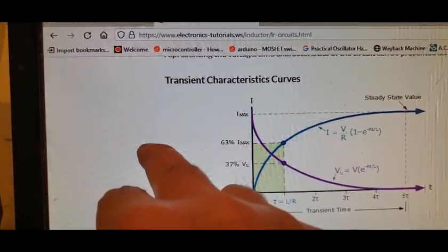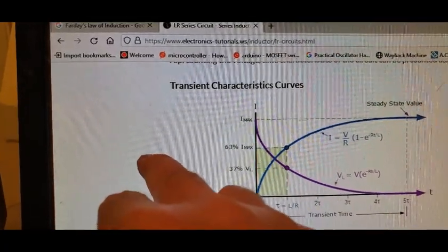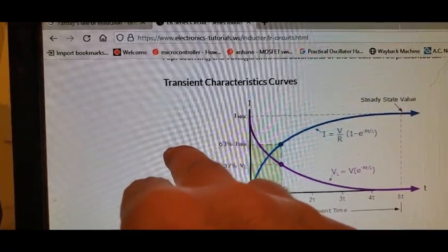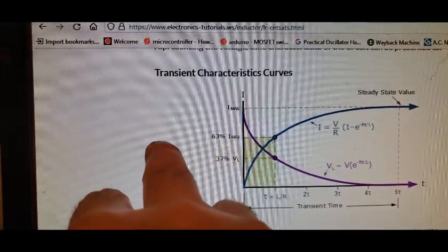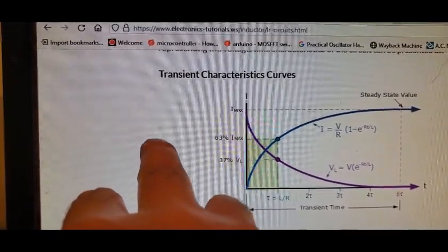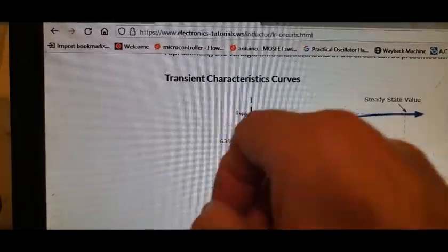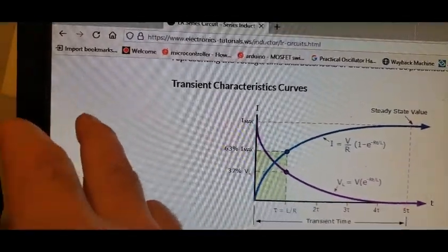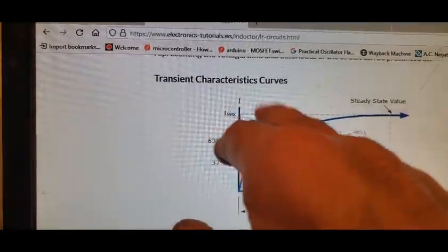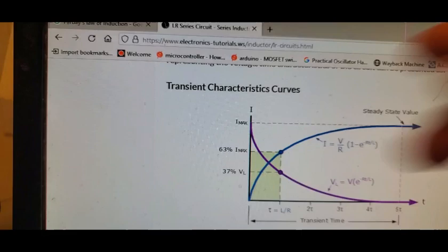Isn't that bizarre to think about? That the resistance has no effect on how quickly the coil is discharging. Now, resistance does have an effect, but what it tells you is that the big boss is the dynamic resistance, this stuff here, and that the straight line DC resistance is negligible when you have a changing field that's oscillating all over the place, changing magnetic field.